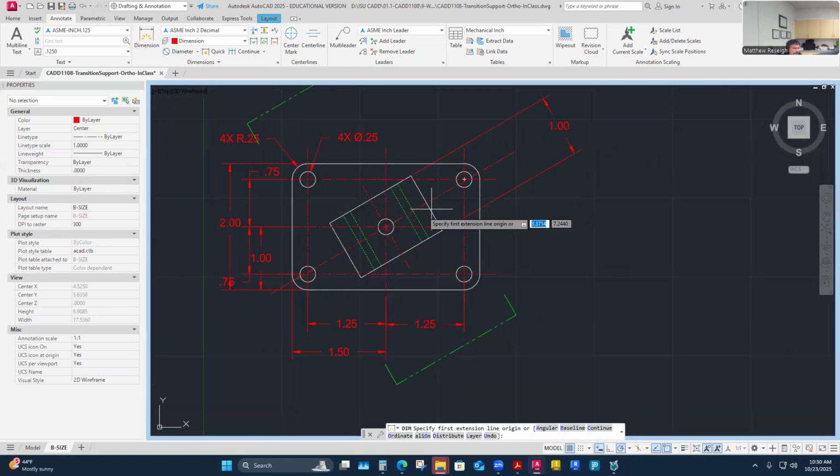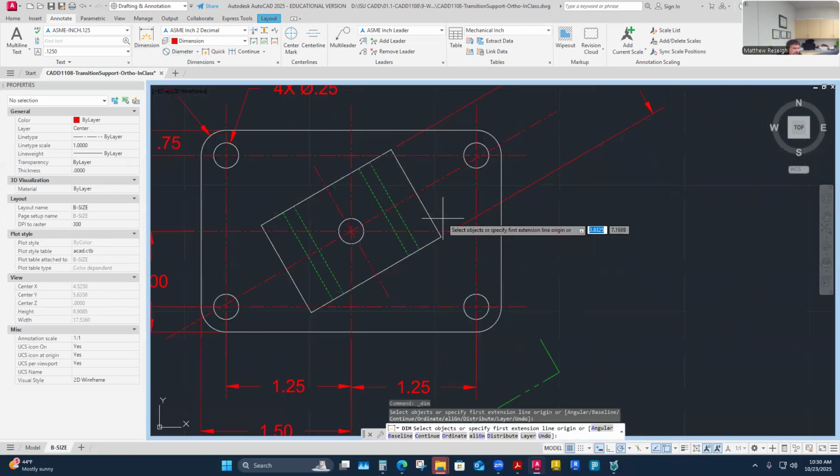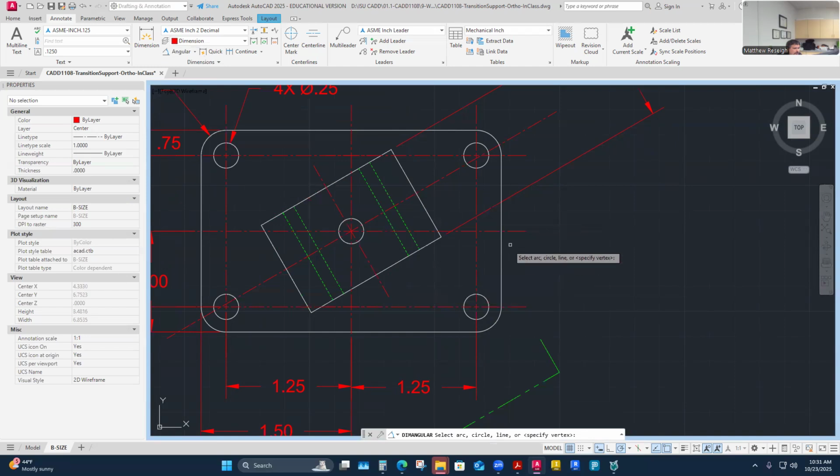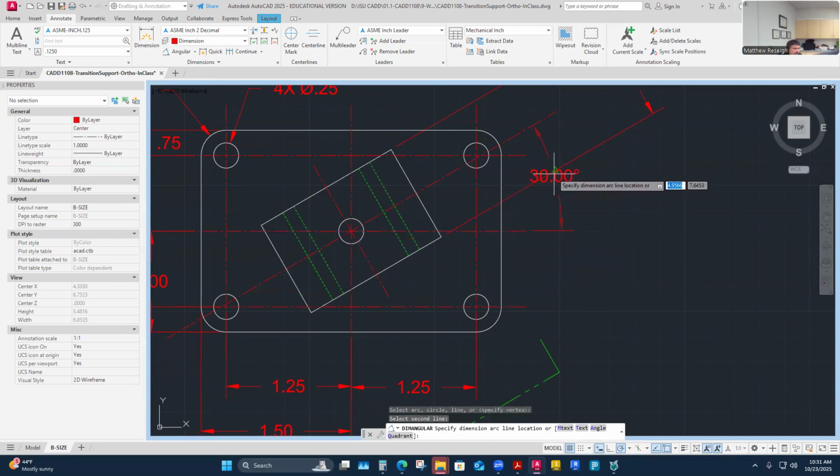Here's one way I'll think about it. I'm going to worry about how it's twisted first. Maybe the first thing I need to locate is that twist. So I'll break my rules a little bit, and I'll say I'm going to use an angular dimension, and I'm going to make it a critical dimension. I'm going to say off this controlled center line to its center line, this is going to be a critical dimension to have.